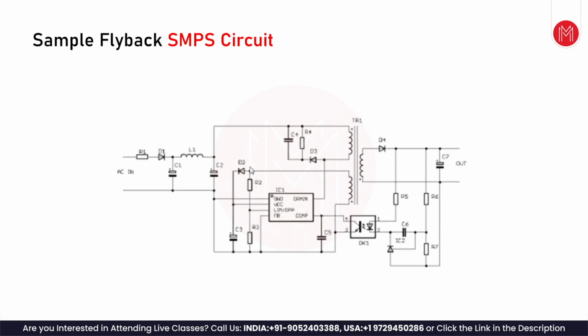It has a few other inputs. This is a limit input, and then a feedback input, and then a compensating input. These inputs are used in regulating the voltage, duty cycle, the current, and all that. So this limit is for adjusting the current. The ratio here adjusts how much current this can deliver. We'll look at the data sheet shortly and read about those things there.